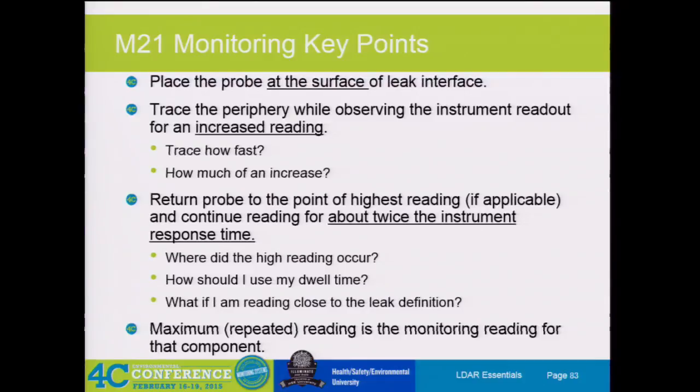And so in here, I think there is a pyramid. I don't know on what page, but it's our recommended time values for what you should set the scan times to in your LDAR program. Most folks, and contractors, all have their own set. A lot of it's been derived based on the pyramid that Buzz Harris put together, who actually co-authored Method 21. A lot of folks have tweaked it based on units or their own company policies, to make sure that this was getting done correctly.